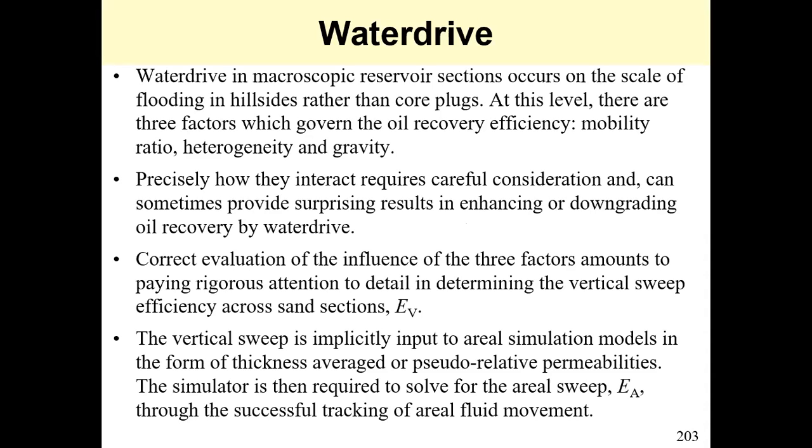At this level, there are three factors that govern oil recovery efficiency, which are the mobility ratio, reservoir heterogeneity, and gravity. Precisely how these three factors interact requires careful consideration and can sometimes provide surprising results in enhancing or downgrading oil recovery under the water drive.